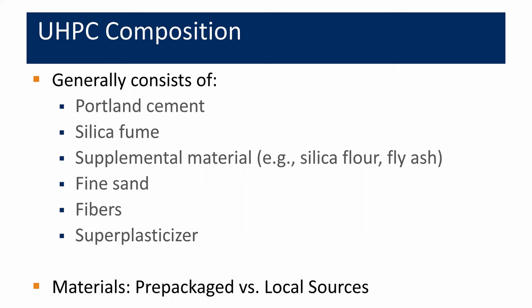Primarily, it's going to have silica fume. Almost every UHPC mixture currently being developed has silica fume, though there are a few exceptions. The silica fume is really important because it's going to be the finest material in that system. And so if you're trying to get a very dense system, you need to have a very fine material that can fit in and fill those pockets between the particles.